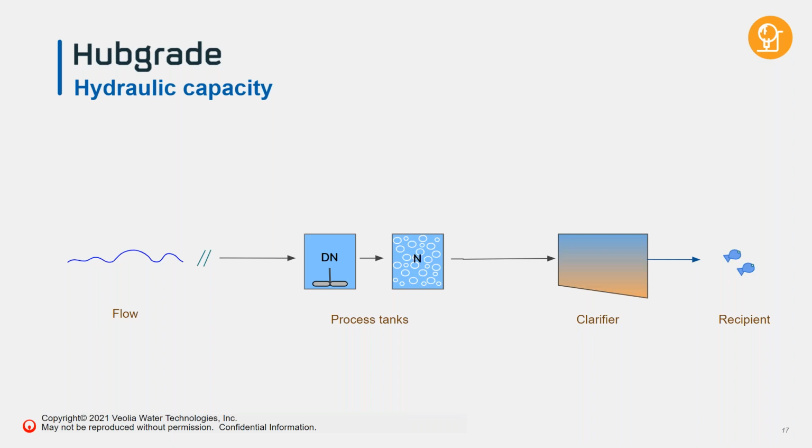Of course, here it's in the case where you probably have total nitrogen requirements. But this is, of course, just an example. So you'd have your load, it comes into denitrification, and then the nitrification, goes through the clarifier, where the SS is sorted, and you've got your clean water that runs out to the effluent, and you keep the fishes safe.